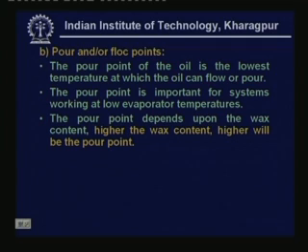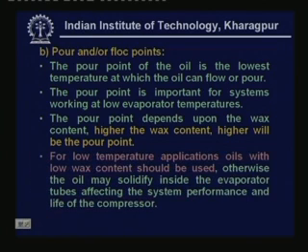Okay, and it is found that the pour point depends upon the wax content. That means higher the wax content, higher will be the pour point. And for low temperature applications, obviously we require oils with low wax content so that we can have a low pour point.